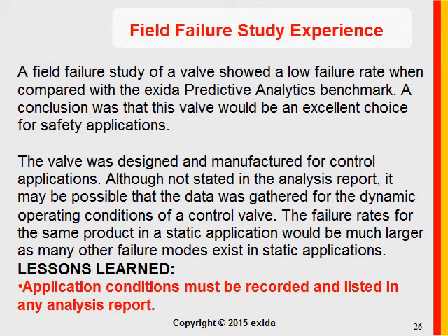I see a question. It seems you place more faith on predicted lambdas using FMEDAs than field data. And certainly you pointed out some good examples of this. Yes and no. What you need to know is the information in a previous web seminar where we explained how it's important that any predicted lambda be based on field failure data that's already been validated.